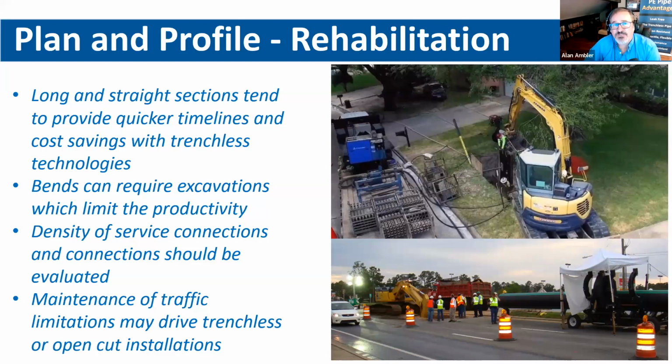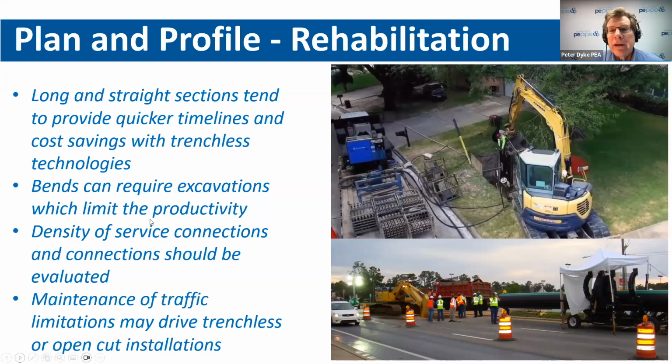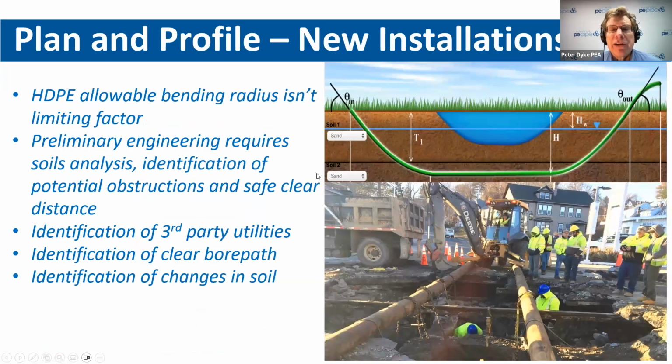Depending on the size of the program, the city of Houston is one of the largest consumers of HDPE for pipe bursting and gravity sewer, and they've gotten the cost down to $30 to $50 a linear foot, which is cheaper than cured in place pipe in that area. So that's a pretty good cost for pipe bursting. Yes, Pete. So I'd say, depending on who asked the question, give us more detail on where your project is. We'll put you in touch with somebody to give you a good cost estimate.